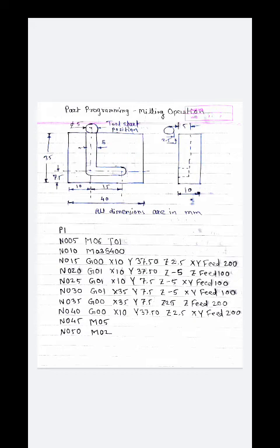lower the cutter. Okay, here I am going to explain the axes. The 40 mm edge is horizontal, that is the x direction. The 35 mm side edge is the y axis, and the vertical, the spindle, the end mill cutter's axis is the z axis. Okay, so any vertical movement is a z axis movement, that is the cutter's movement.